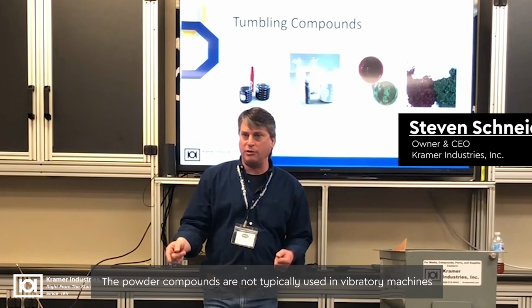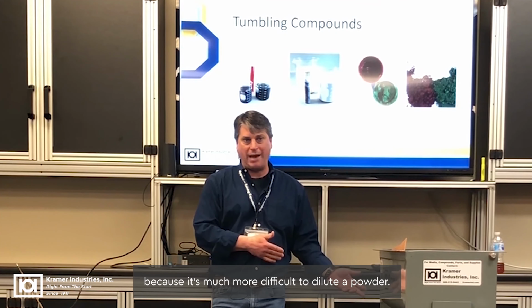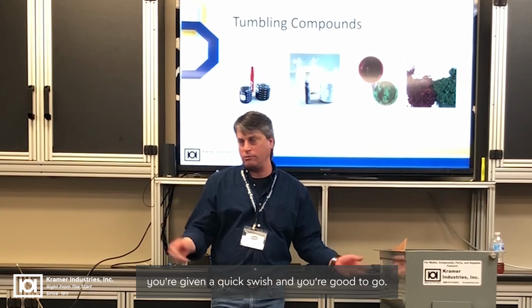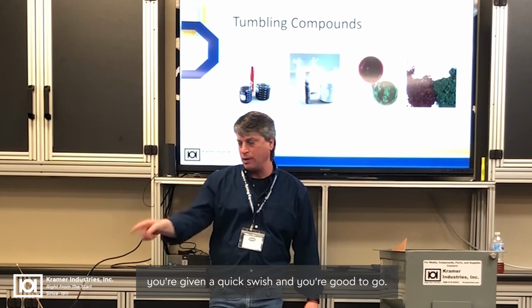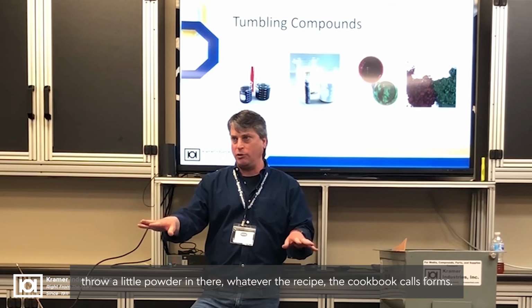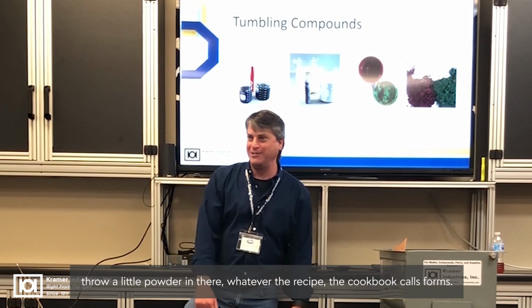The powder compounds are not typically used in vibratory machines because it's much more difficult to dilute a powder. You have to mix it, whereas with the liquids you just dump in and give it a quick swish and you're good to go. Powders work great in barrel tumblers because you just put the water in there, throw a little powder in there, whatever the recipe, the cookbook calls for.